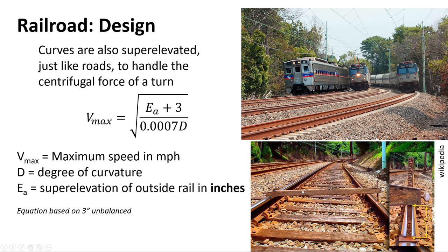It's a little hard to see, maybe it blends into that color, but there's a level on this. And so you set this up, and then you crank up the low end, whichever rail is lower, you crank up this measuring device until the level bubble up here shows that you're perfectly level, which would be this bar is level. And then this unit is measuring the distance from the lower rail up to the level that the higher rail sits on. And they measure it in inches, right?